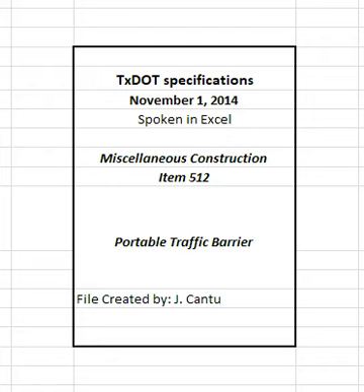Construct barrier in accordance with Item 420, Concrete substructures, to the dimensions and cross-sections shown on the plans. Provide forms and cure concrete in accordance with Item 424, Precast concrete structural members, fabrication, TxDOT. Provide a rough texture to the bottom surface of single slope or F-shape barriers and to the top of low-profile barriers similar to a wood float finish.